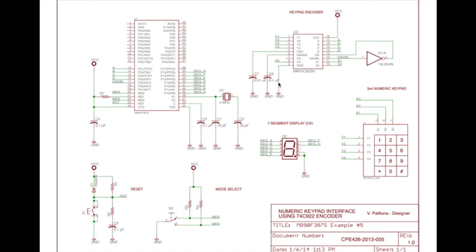So that's 0.1 microfarad for the first one. The DAVBL pin, number 12, is connected to an inverter, and the output of the inverter is connected to output enable. So when you press any key, DAVBL will be 1, inverted becomes logic 0, which is connected to output enable. To enable the output, the output enable pin, pin number 13, should be logic 0.